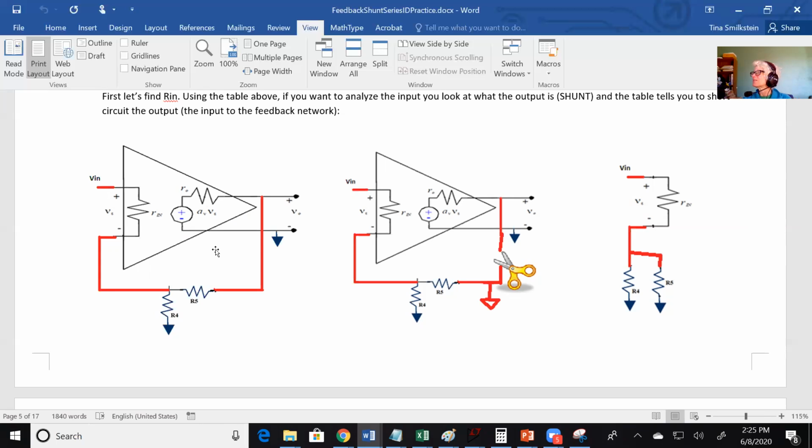Oh, okay, so instead of just arbitrarily choosing ballpark resistor orders when we try to get the gains of these things set up correctly, we should choose them specifically to make sure that our R in and R out requirements are met. Yes. Okay, cool. Thank you. Okay. There's 3 more to go.